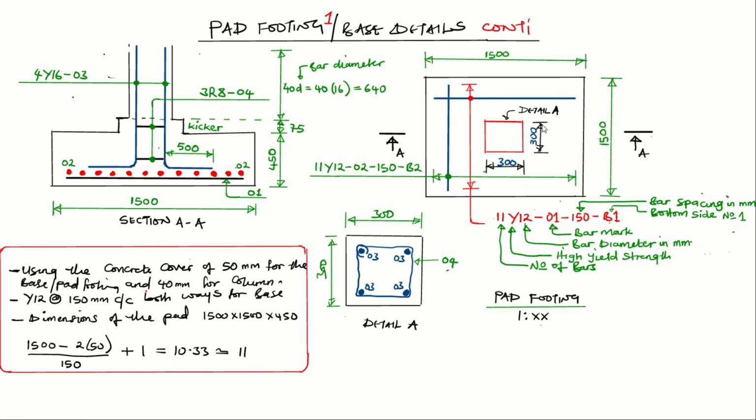Or if you want, you can call it the way we've called it from the base here, as Detail A. You point an arrow at this cube. Now this cube, when you look inside, you're going to look at these links that were being tied, the black ones here. They're going to be represented by this outward circle that you're seeing here. Then the starter bars are going to be represented by these shaded circles that you're seeing here.